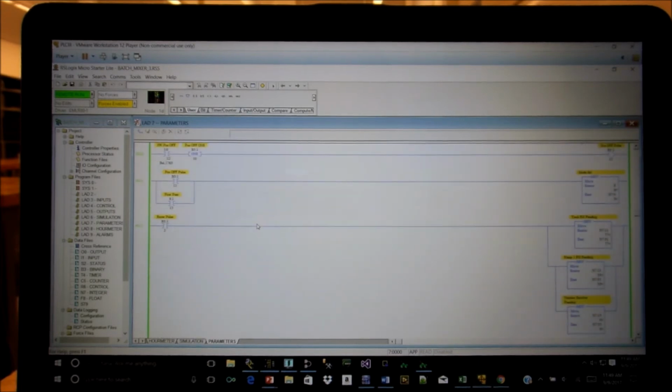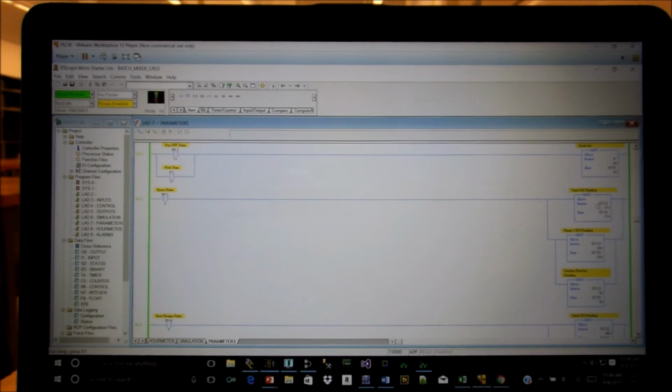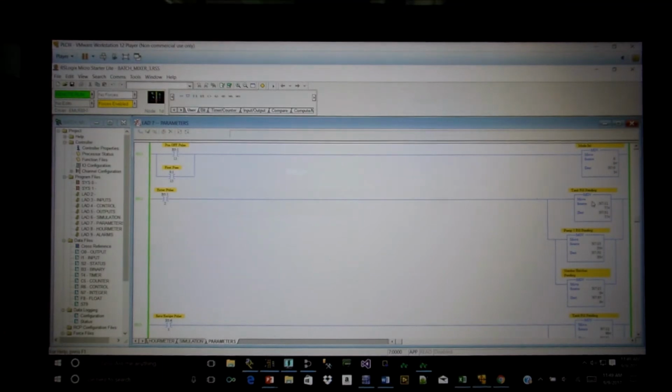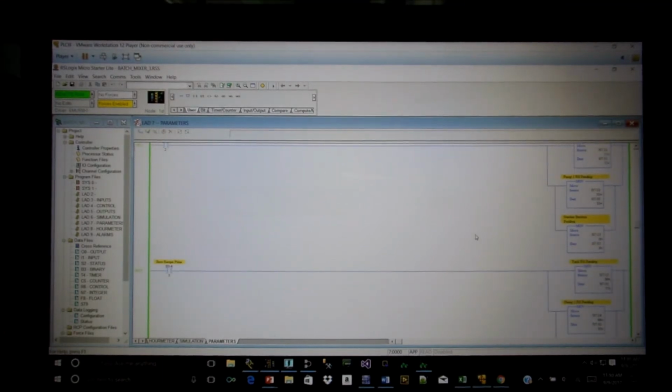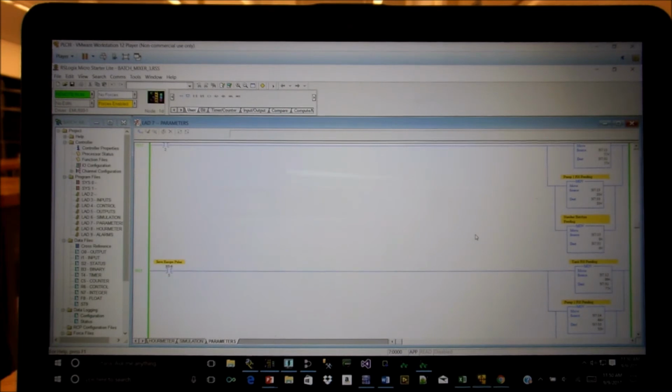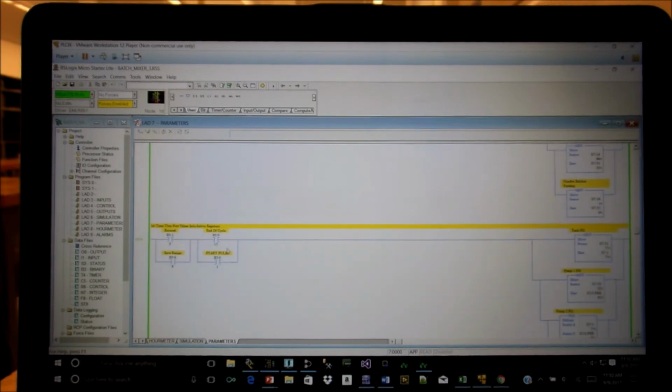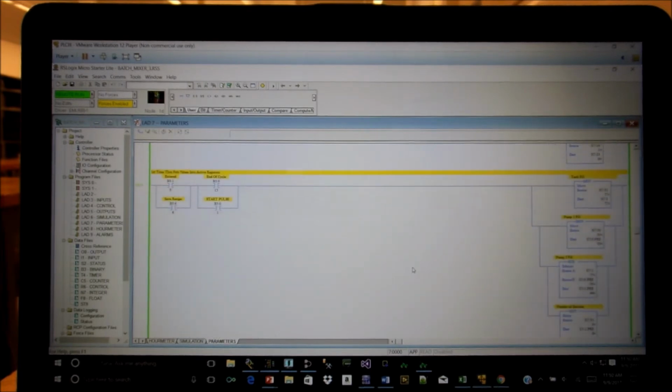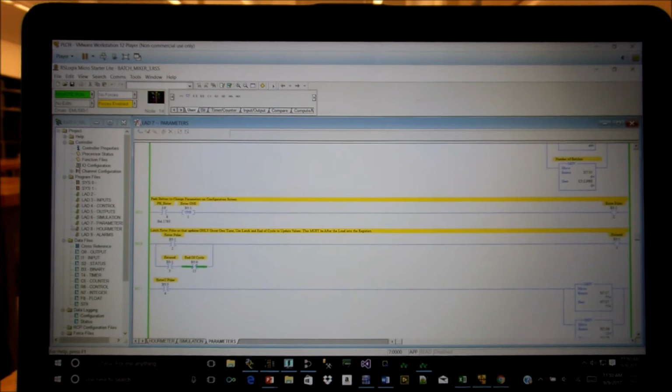But then, because we're setting things from the configuration register, we move everything into a pending register. So when we hit enter, it moves into a pending register. But then it stays in the pending register until it actually sees the end of cycle pulse or a start pulse to run a new sequence. And that's when it moves it from the pending register into the active working register. So the simulation and what we're doing with setting up parameters is pretty important.